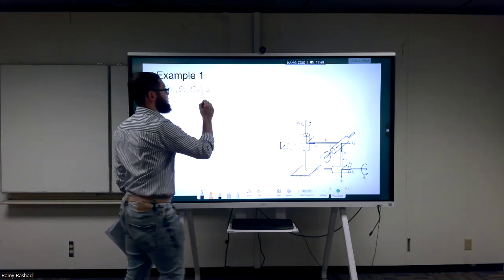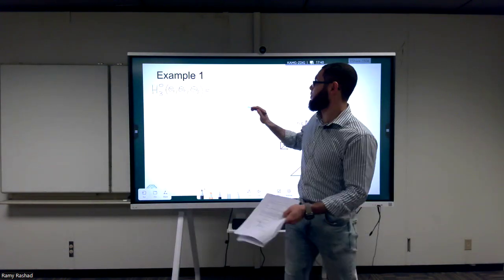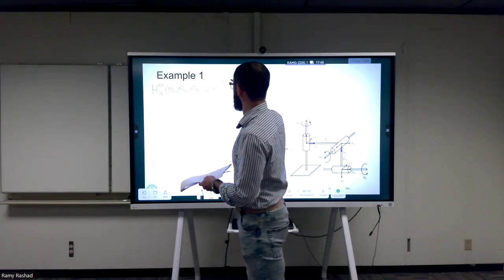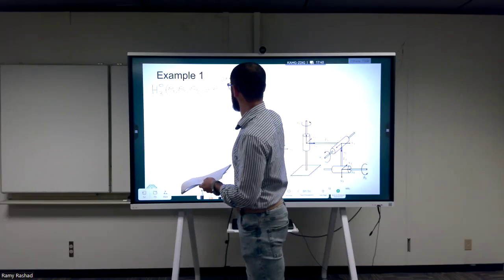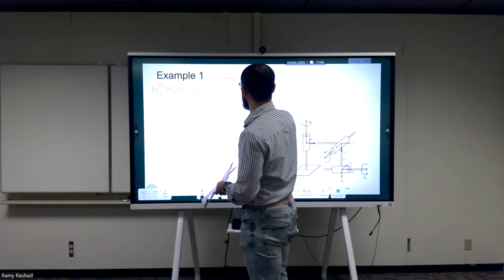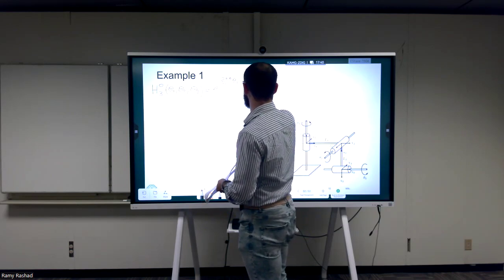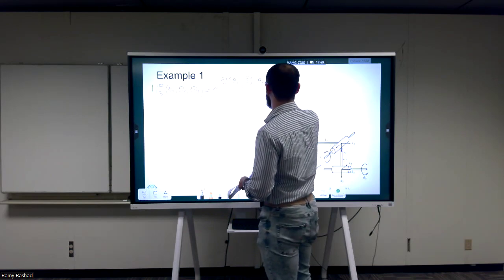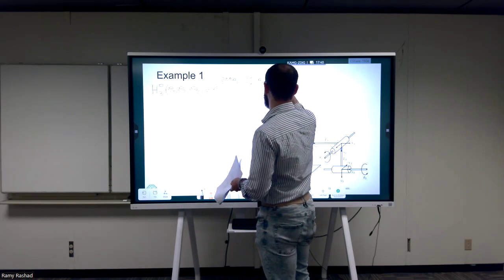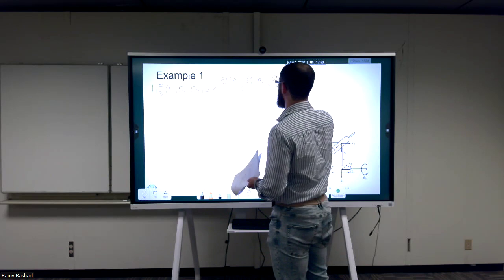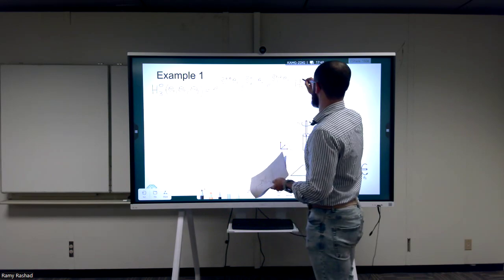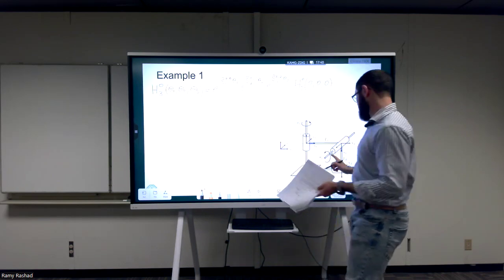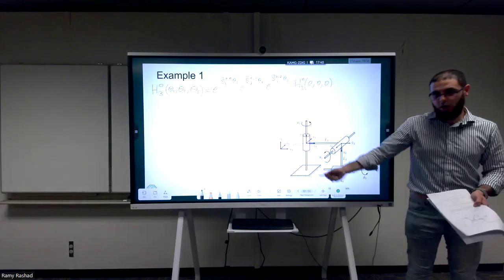And how is this calculated? Again, from the product of exponentials formula, we have the exponential of S1 with respect to 0, expressed in 0, in tilde form, multiplied by theta 1. Then we have the exponential of S2 with respect to 1, expressed also in 0 in tilde form, multiplied by theta 2. And we have the exponential of S3 with respect to 2, expressed in the 0 frame, multiplied by theta 3. Then we multiply in the end by H3 0 when all values are 0, so we have 0 theta 1, 0 theta 2, and 0 theta 3, which is what we mean by the home configuration.